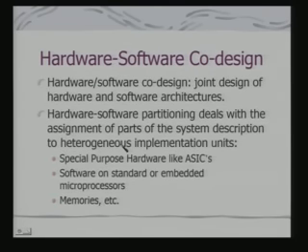So, when we have represented the overall design, then we have identified the different components. If you remember the UML representations, we have got, say, the activity diagram, which has represented the different tasks along with the concurrency indications. The task diagram is also a specification of the tasks that are to be performed in a system to meet the functional requirements, and the constraints can be imposed there. Now, once we have that kind of representation, we need to map these into hardware and software.